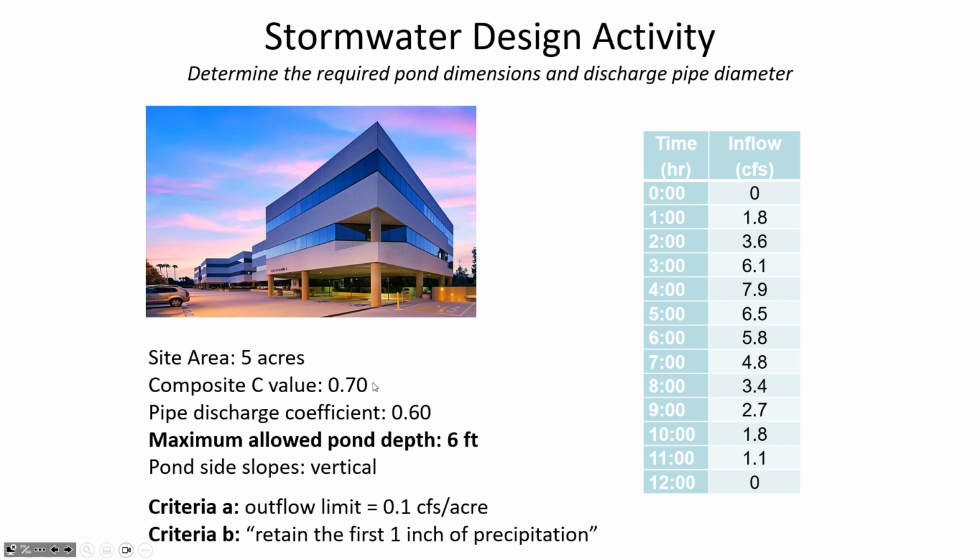And so that's one of the reasons we don't want ponds to get too deep, is that the wind doesn't stir it and mix it like otherwise it would. Another problem is that if the water's really deep, then it can be a drowning hazard if it's not got a fence around it, because ponds are often in parks, areas that children are accustomed to going to. If it's a multi-use pond where it's a park and also stormwater detention when it's really wet, then suddenly you've got the risk of children in the vicinity of water that's not fenced off.